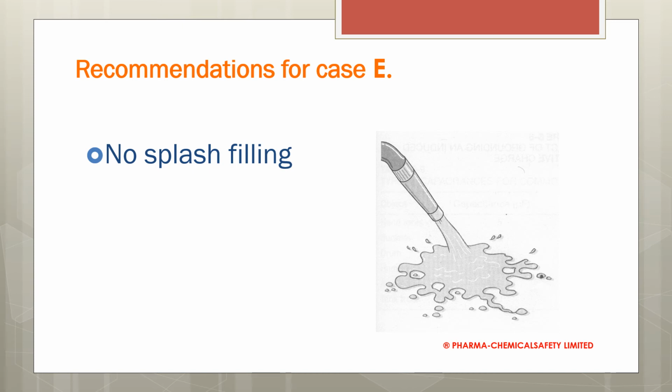Then, if you're going to design the system and measure the oxygen according to NFPA 69, you need to go 40% below the LOC if you have oxygen detection, and 60% below the LOC if you don't.